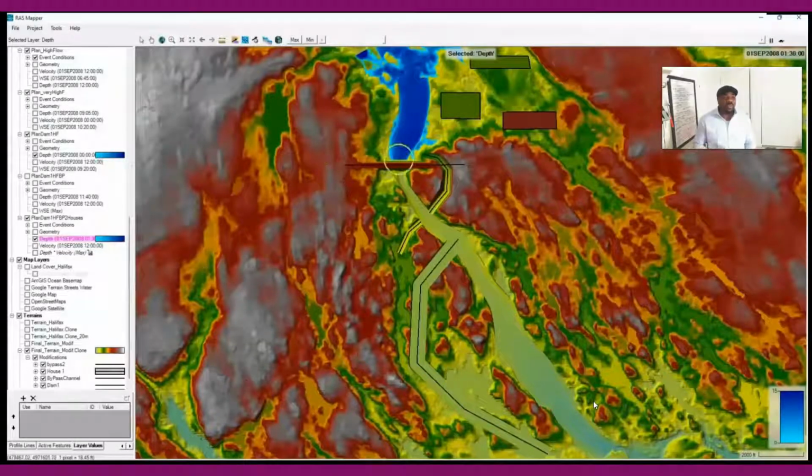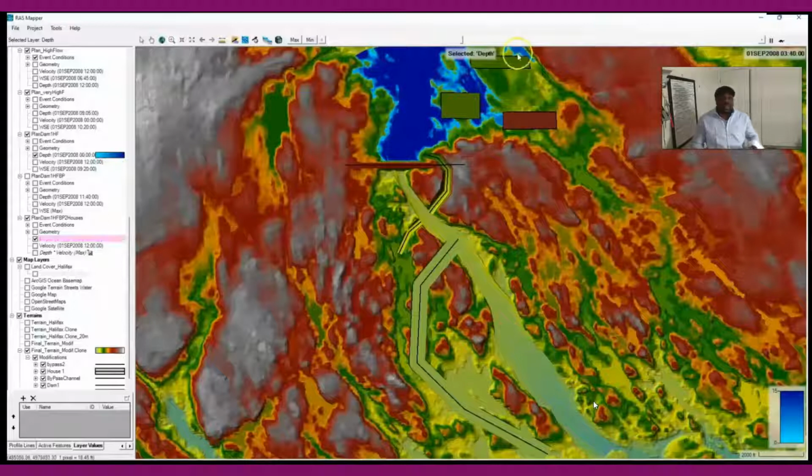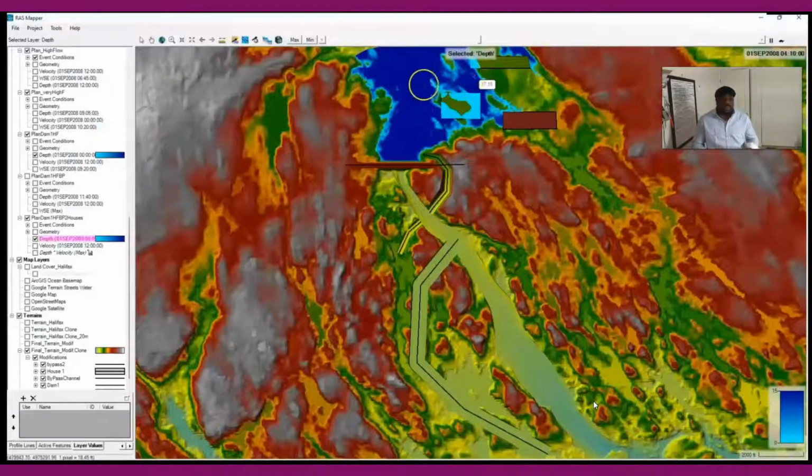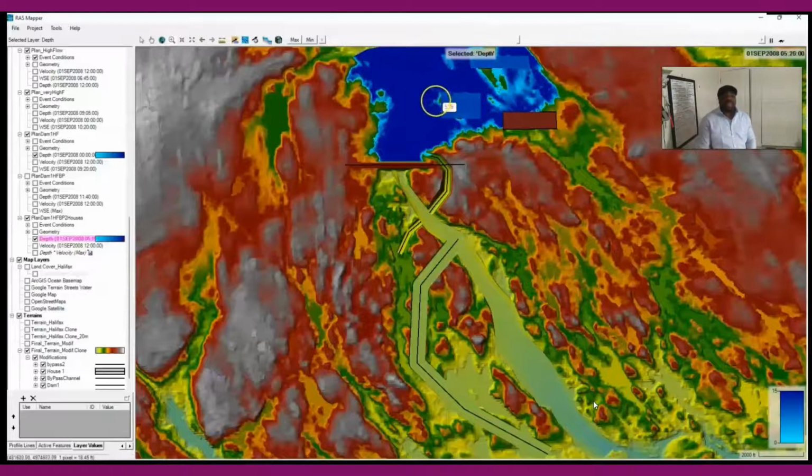The dam is going to stop the water, so water won't propagate in our field, and it's going to build up. Also, you can see here the house, depending on what kind of coefficient, what kind of roughness, or Manning, and what altitude of the building, won't be flooded until the water builds up and starts to inundate the building. You can see here the buildings are going to be flooded depending on their height. If the building is not very high, it will be flooded, but if the building is very high, it will be stopped. And you can see the channel here.